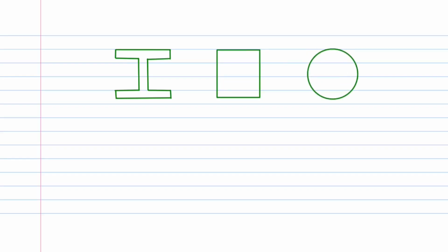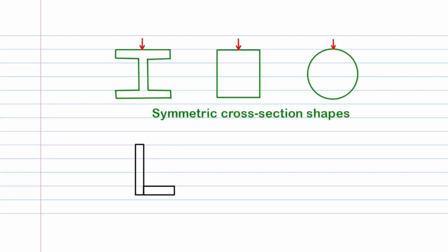Before we take up some examples for finding the moment of inertia of some complex shaped sections, it is worth noting a point that somehow got missed in the last lecture. One of the assumptions we made during the derivation of the flexure formula was that the sections are symmetric about the vertical y-y axis or vertical plane passing through the centroid, or with respect to the load applied.